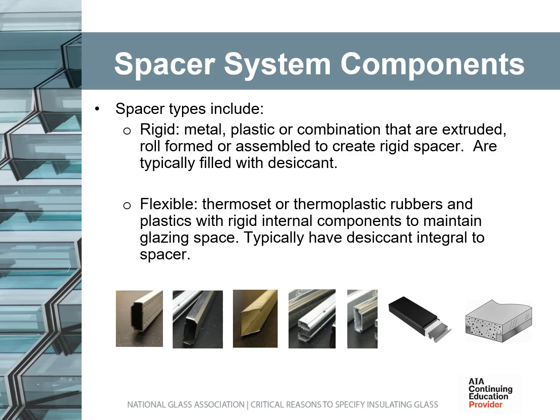There were also changes to the material of the spacers. Instead of using aluminum, which is very conductive, the material was changed to stainless steel that transfers energy at a much lower rate. And as requirements accelerated beyond that, plastic was introduced, which is far less conductive than both aluminum and stainless steel. Most of these new spacers with plastic were hybrids and still use aluminum or stainless steel to keep the benefits of having the inorganic surface aluminum and stainless steel provided, but used plastics to cut down the paths of energy transfer even further.